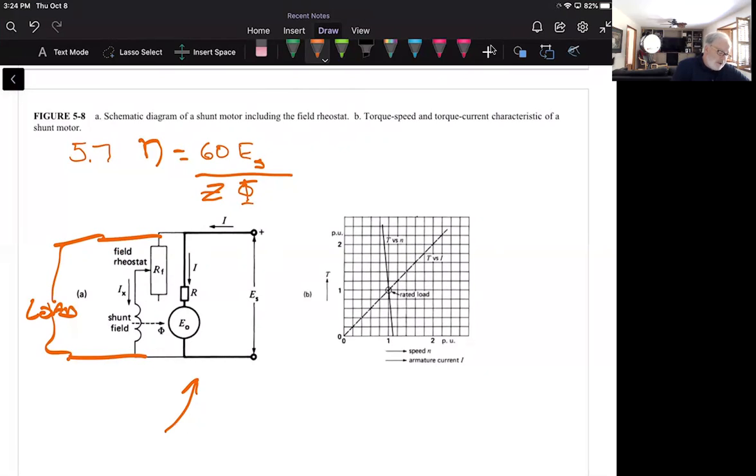And when I connect a load to this motor, what happens is, if the mechanical load is applied to the shaft, the small no-load current is not enough to provide the torque, so the motor begins to slow down, okay? Now, this causes the CEMF to diminish. When the CEMF diminishes, the current increases, because the difference between source and armature voltage increases. So when that happens, we get a higher current. When we get a higher current, we get a higher torque.